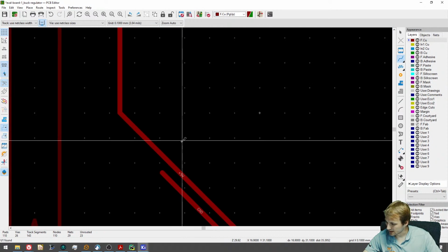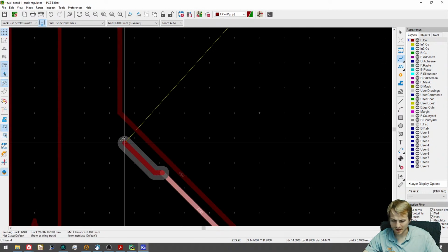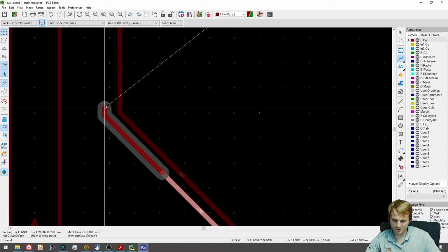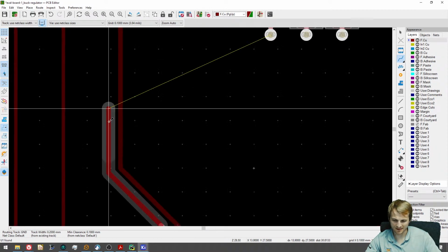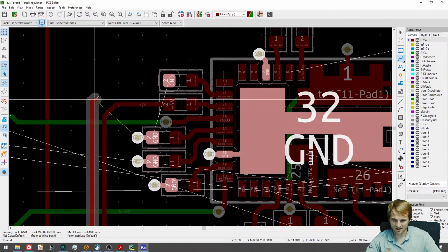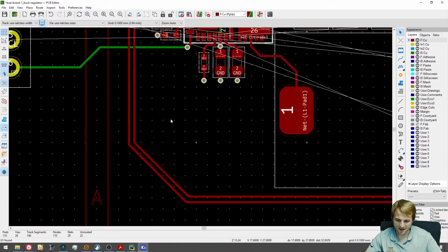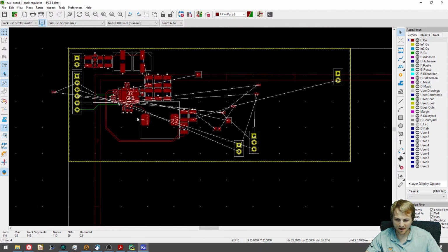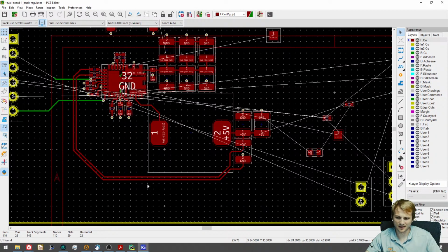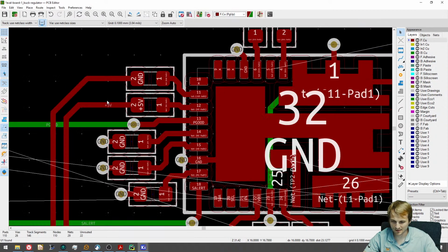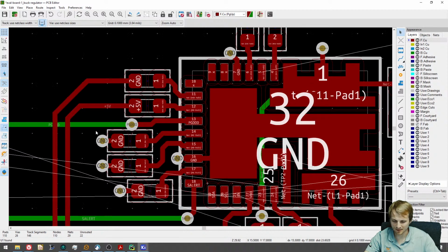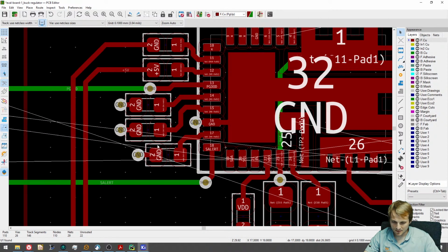They also have a 1 mic cap between the sense pins and the load lines. Yeah, when we originally saw it, that was the first thing I said: if you're going to have an RC filter, which makes sense, where's the C? So yeah, that makes total sense that they would want that there. I see the advantages of this sort of configuration compared to the standard voltage divider setup, but I guess it's a bit more of a pain to lay it out. I'm assuming the caps will just throw right in here. Okay, so those are good.